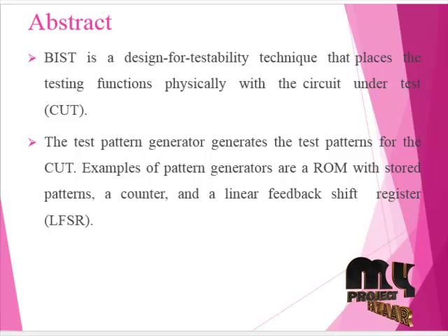Conventional scan-based test hybrid schemes, due to the high data activity associated with scan-based test operations, may consume much more power than the circuit under test was designed to function under, overstressing devices beyond the mission mode. Reductions in the operating power of ICs in test mode have been of concern for years. Full toggle scan patterns may draw several times the typical functional mode power, and this trend continues to grow, particularly over the mission mode's peak power. This power-induced overtest may result in thermal issues, voltage noise, power drop, or excessive peak power over multiple cycles, which in turn cause yield loss due to instant device damage, severe decrease in chip reliability, and shorter product life.